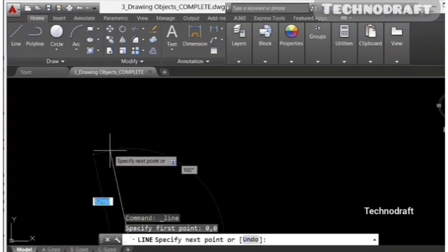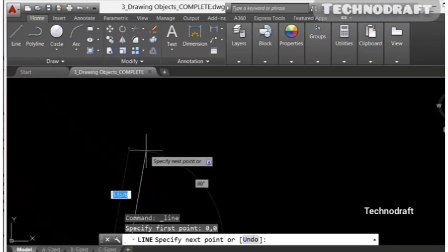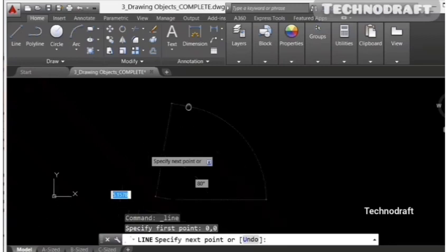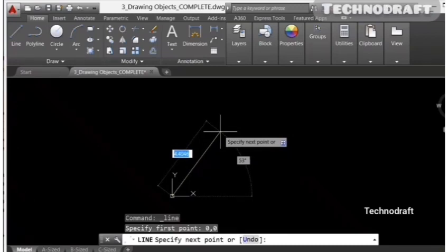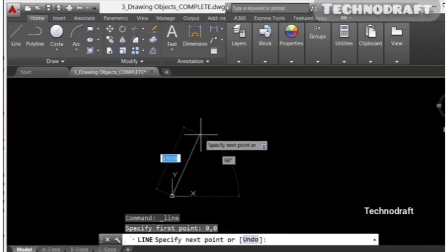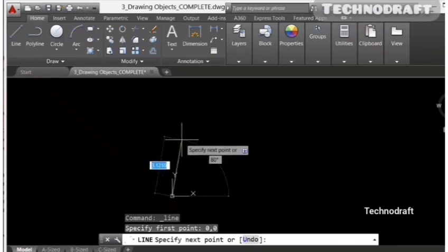And you will notice now that the line is at the bottom of the screen a little bit there. Don't worry, just hold down the wheel on your mouse, pan upwards a bit and you will see a little grayed out line setting there. And as you come up and release the mouse, can you see there is an XY indicating where 0, 0 is, and you can see that our line has started at that intersection of Y and X.